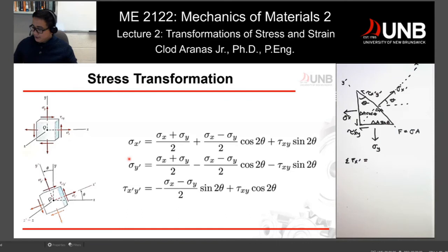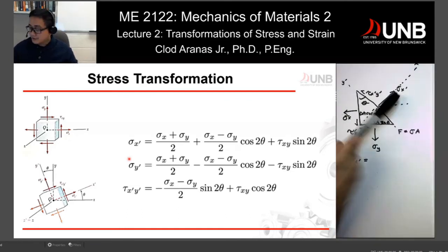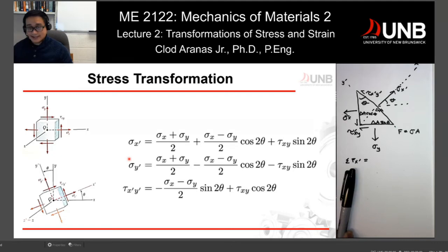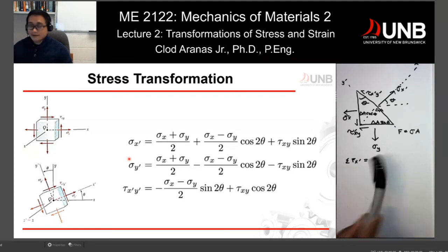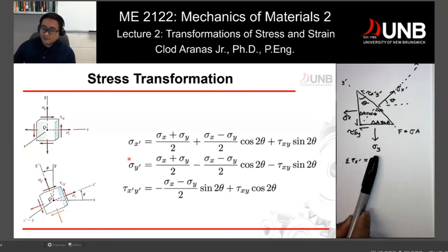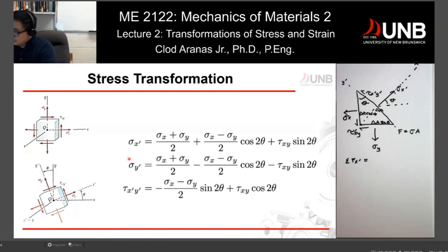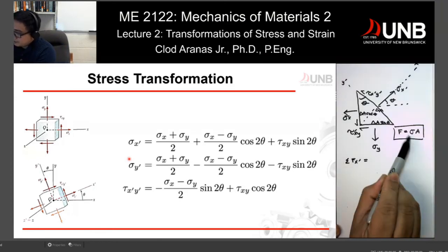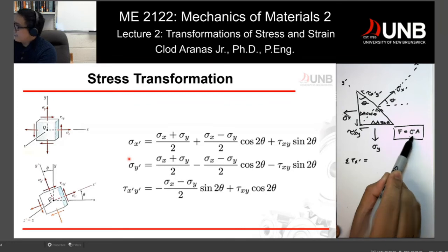Now let's move on. We have all the forces in this diagram, wherein we take a cut at a certain rotated axis because we want to take the equation from there. Now we can sum forces along our rotated axis, x prime, but these are stresses, not forces. So again, that's why we need to use this equation here: stress times our area.